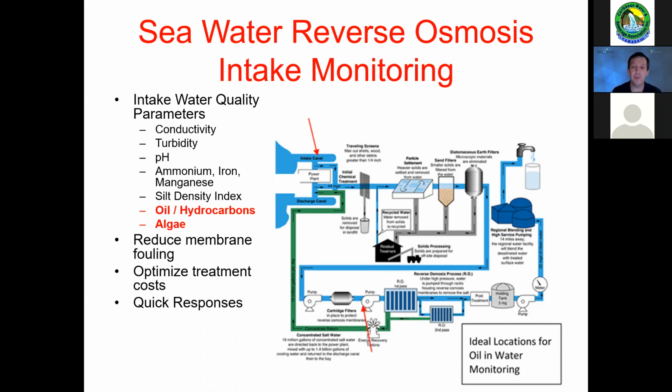For small desalination plants, maybe at a resort, it may not be as important because the size of the membranes is not very large. But for large industrial plants or for municipal water intake, sometimes these membranes can be $500,000 to $2 or $3 million worth of membranes, and 1 part per million of benzene could produce some significant damage to them. So there's not a significant risk to this, but there are significant costs to fouling.